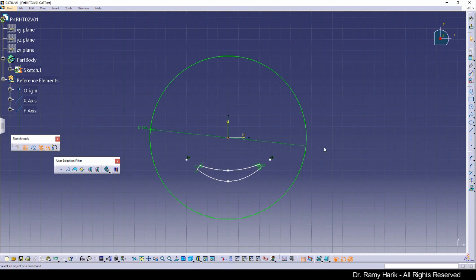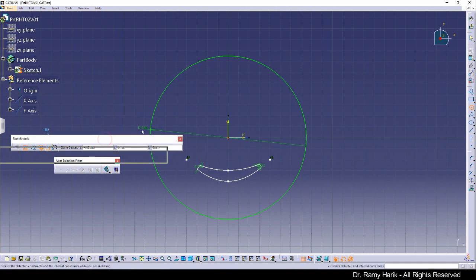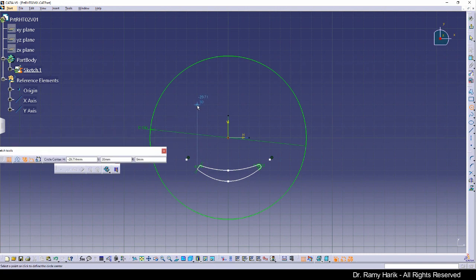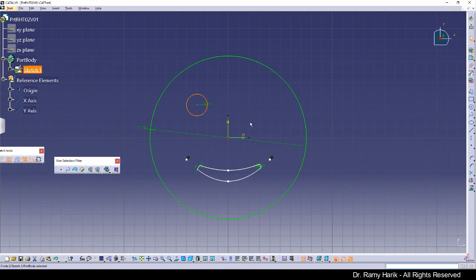this smiley. We're going to click the circle icon and select the point minus 30, 30. So in case we're not on the grid, we can actually adjust. So minus 30, 30. And we wanted a 10 millimeters radius. So I'm going to click on tab. You can see where it's changing. And I'm going to put 10 millimeters here. And then it would start, create it.